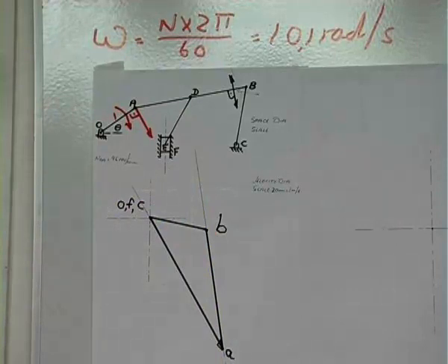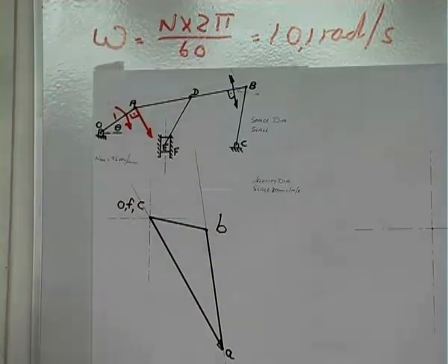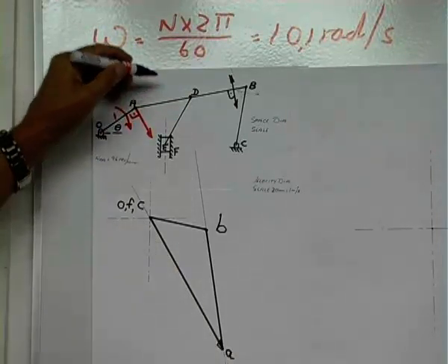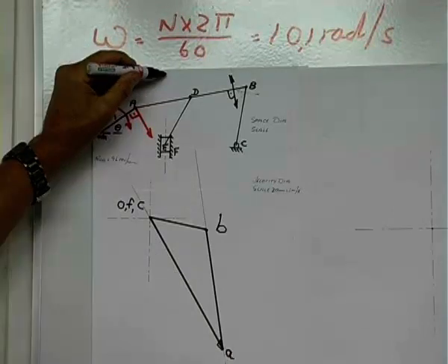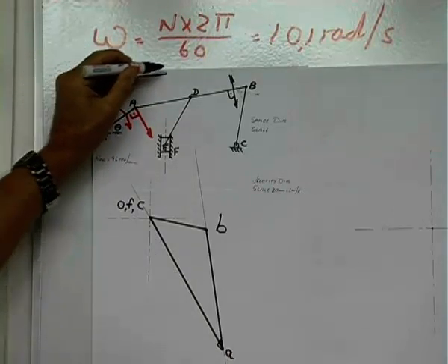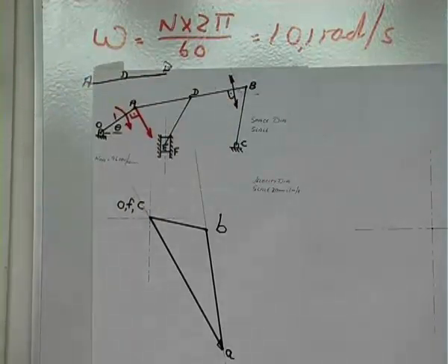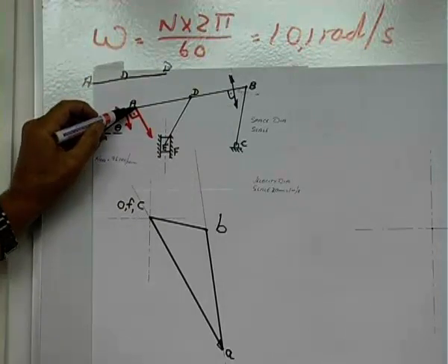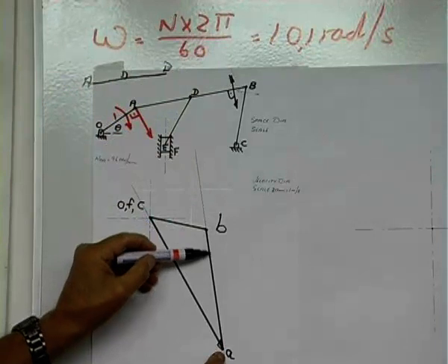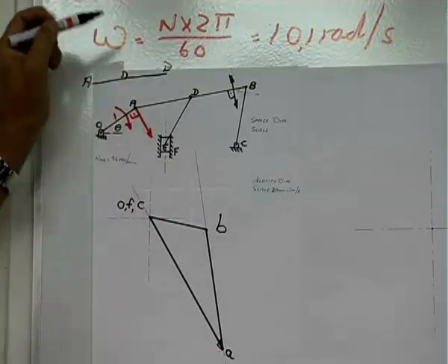All right. The next will be to go and plot D on my velocity diagram. We can see on our space diagram, A, D, and B are on one link. So where is A? There's A, no? There's B. So somewhere in between, we can plot D. Use ratios.